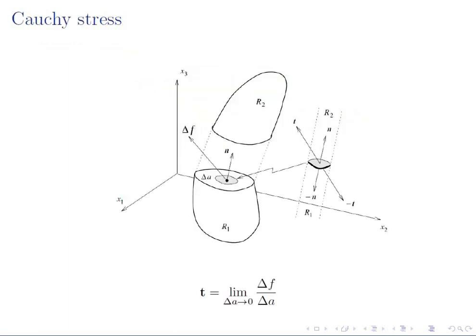Now in mechanics of solids, most of the time we are interested in finding the effect of forces which one part of the body exerts on another part of the body. In order to do that, we make an imaginary cut in the body, and then we try to find the forces which are acting on that imaginary cut.